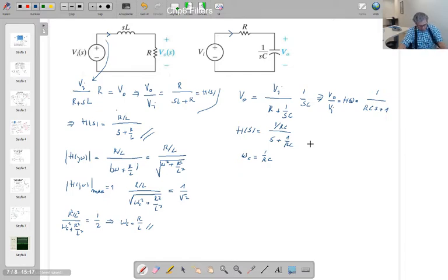Now, up to now what we have done, we analyzed a circuit which has two elements connected in series and took the output from one of the elements. And we have seen that the modulus of these functions changes with respect to frequency, giving a low pass filter. So in general I can say that this circuit is a low pass circuit.